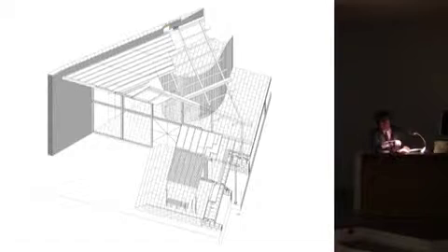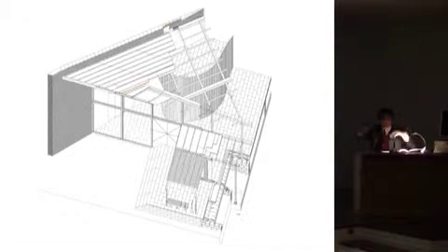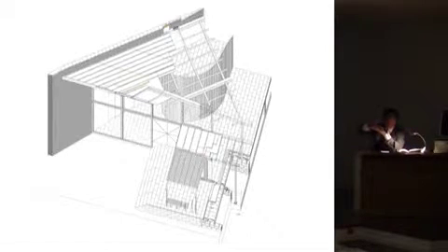I wanted to create these stainless pillars because it's in the sea, and I wanted to work on this nice canopy, sieving the light. That's quite widely used. So the pillar, I wanted to do a cross pillar, cross shape, because then it receives the T-shaped beam and it articulates perfectly well to build the arbor. So the cross pillar, stainless steel, because it's next to the sea, and of course I didn't want it to rust in 4 days. Stainless steel, good.